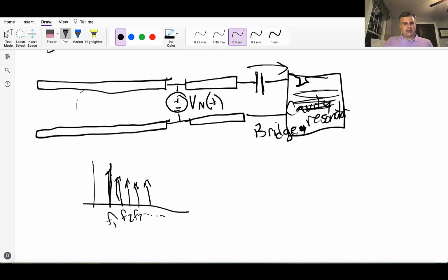And what you learn in cavity resonator theory, or just about any other type of resonator theory, is that the lossiness of the resonator determines how thick these peaks are. In the ideal one that we first introduce in our undergraduate classes at Georgia Tech, those metallic electromagnetic RF resonators are ideal. So we model these as impulses. You physically cannot excite any other frequency of mode or sustain any propagation inside the device in between these discrete peaks.